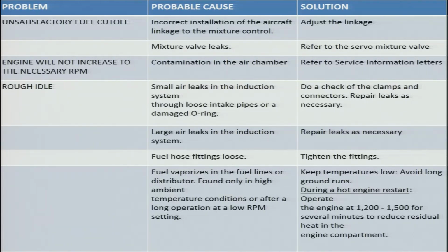Fuel hose fitting loose. The fuel hose fittings might be loose. They may be the reason for rough idle. In that case also the fittings need to be tightened. Then another reason might be that the fuel vaporizes in the fuel lines or distributor. When the fuel vaporizes in the fuel lines or the distributor, then also we may encounter rough idle operation. This is found only in high ambient temperature conditions or after a long operation at a low RPM setting.